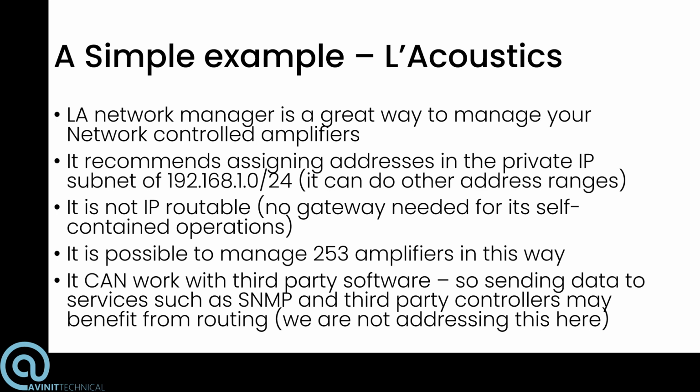Now, the actual control software is not IP routable itself. It does allow for IP routing if, for example, your amplifier is talking to an SNMP service. That's a server that logs information and allows people to monitor this in third-party software. So if you're just controlling your amplifiers, you don't need a gateway. If you're using SNMP to monitor things estate-wide or deal with third-party controllers like Crestron, you'll be very, very well aware of whether you're using these things or not.